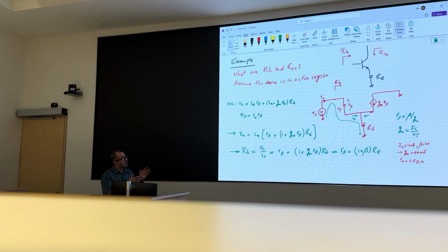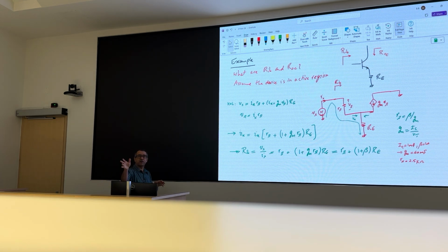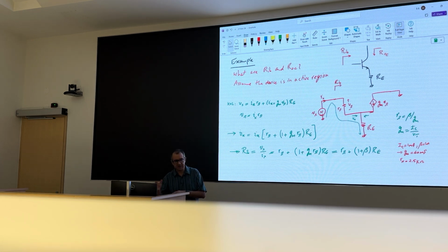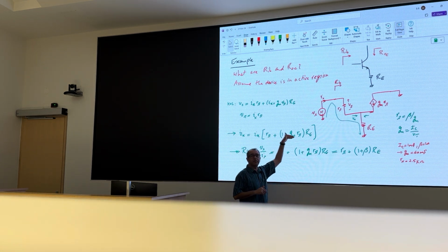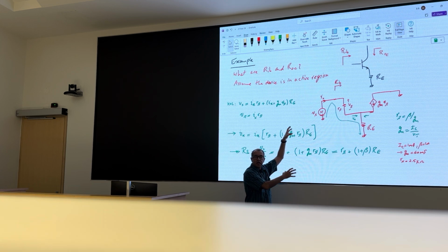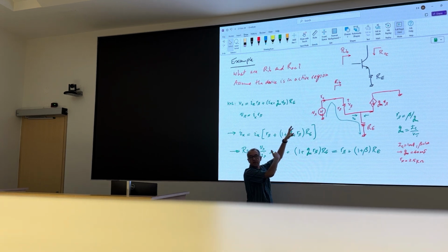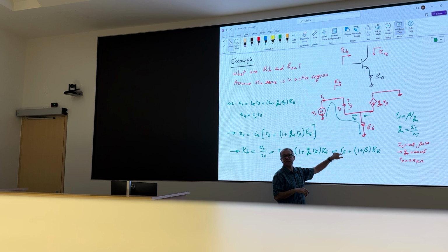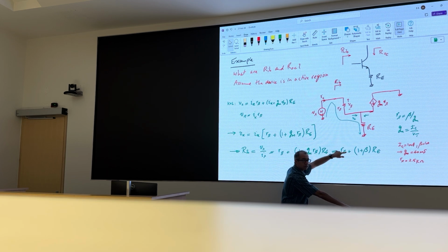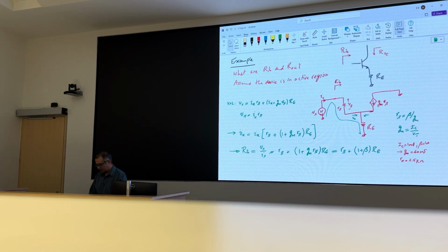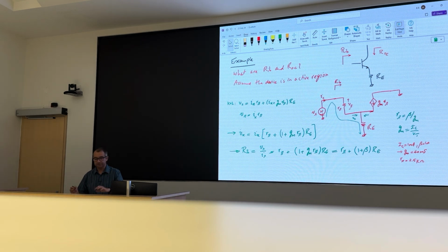But this is beautiful. But this is also, I think, the first rule of BJT impedances. I don't know, maybe they call it the rule of BJT impedances in your book. But anyway, when you look into the base, the equivalent resistance in the emitter circuit appears as beta times larger. And all you have is just 1 over alpha in series. Right? Whatever you have in the emitter times beta plus 1, roughly. Good. Let's look at ROC.